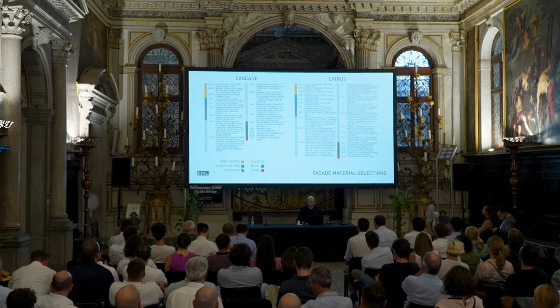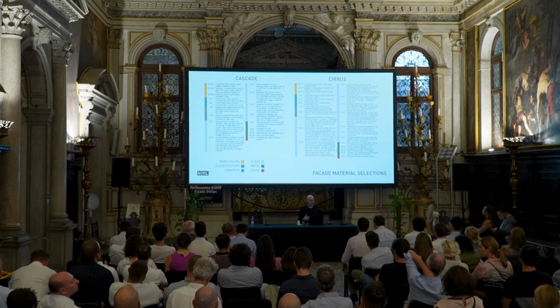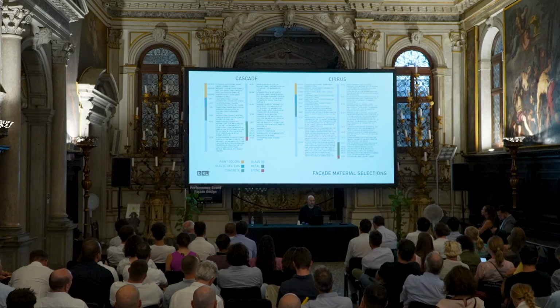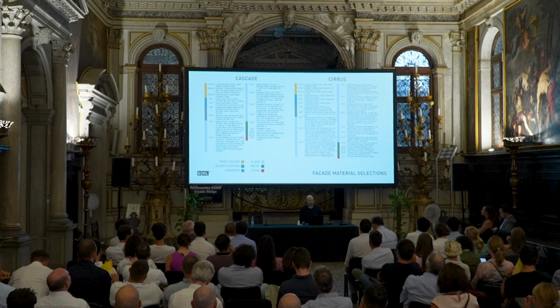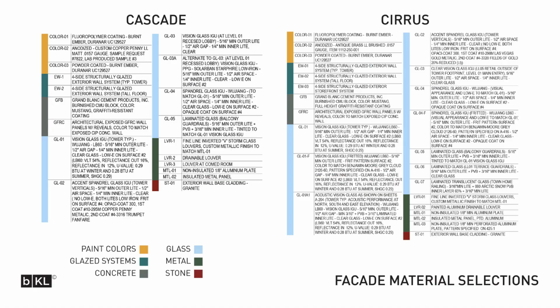So for this, we had to take into account visual qualities of the products that we were analyzing and considering for the project, as well as the performance requirements that needed to be met. From the visual side, we were looking at the reflectivity of the glass, transparency, color and tint, flatness of the glass, while at the same time, all those qualities had to be cross-matched against the requirements of the energy and performance,